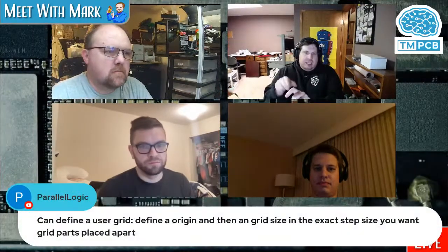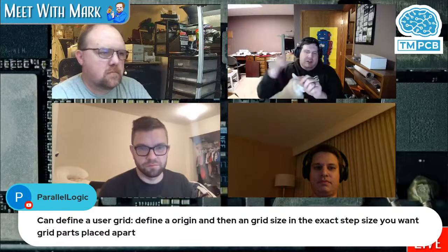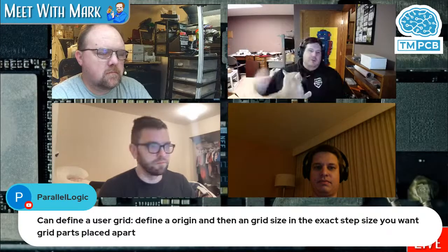Yeah, sounds pretty tedious. For people doing KiCad stuff, KiCad lets you do math in all the text boxes. So let's say you want a key that's 19 millimeters to the left. You can align your other key on top of the one you have here, then hit E for properties, and then you just hit plus 19, and bam, it moves over.